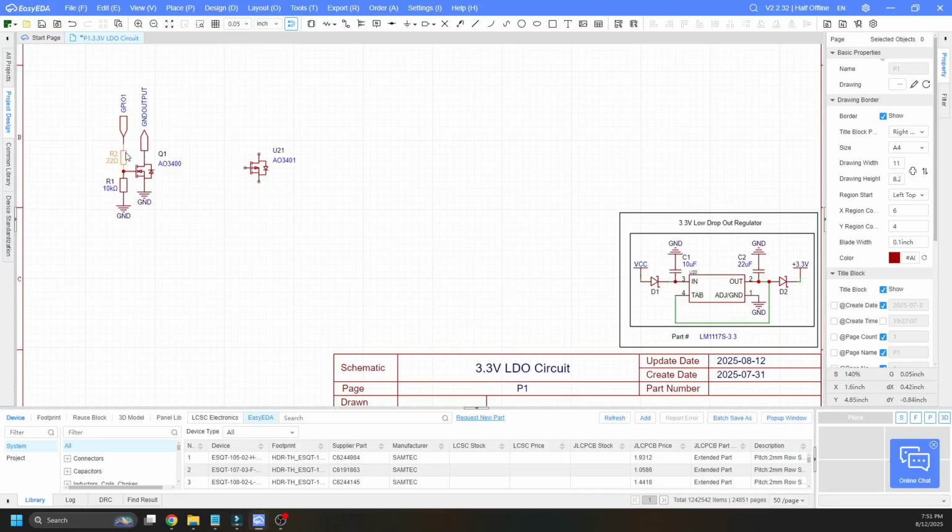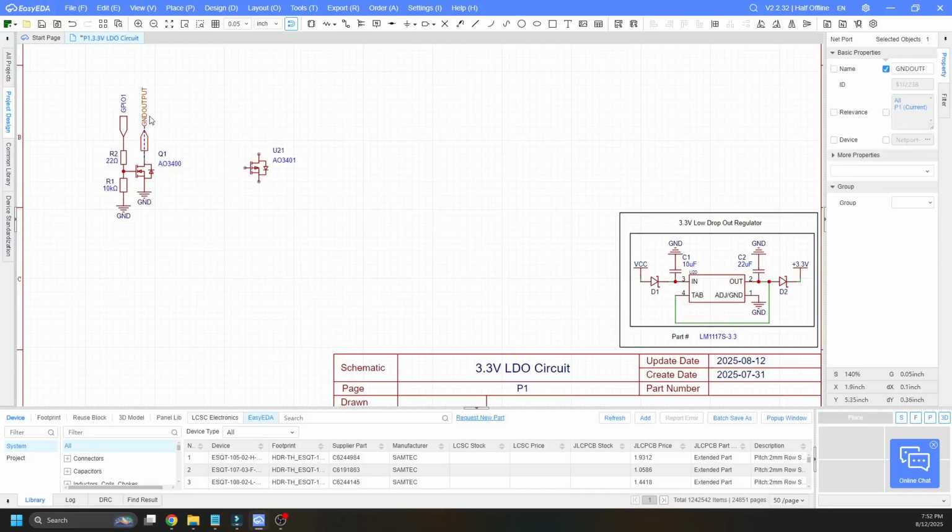Now when it sends that, it's going to overpower the weak pull-down resistor here, and it's going to give a positive voltage to the gate. When a positive voltage comes to this gate right here, it's going to be higher than the source, which is ground. When that happens, it energizes the MOSFET and allows the source, which is ground, to come through and come to the drain side, which we're calling ground output. So this would now be grounded at the output.